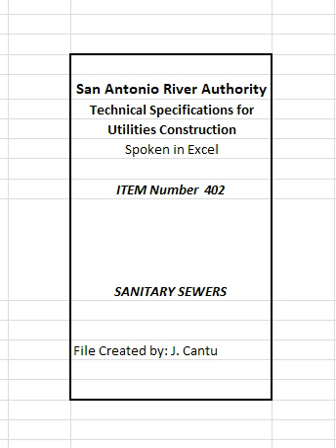All ductile iron pipe shall be continuously and permanently marked with the information described as follows. The weight, class or nominal thickness, and casting period shall be shown on each pipe; the manufacturer's mark, the year in which the pipe was produced, and the letter D or the word ductile shall be cast or stamped on the pipe. All required markings shall be clear and legible, and all cast marks shall be on or near the bell. All letters and numerals on pipe sizes 14-inch and larger shall be not less than 1/2 inch in height.